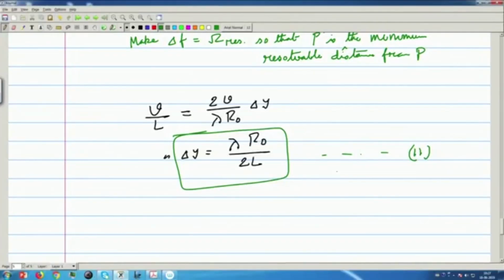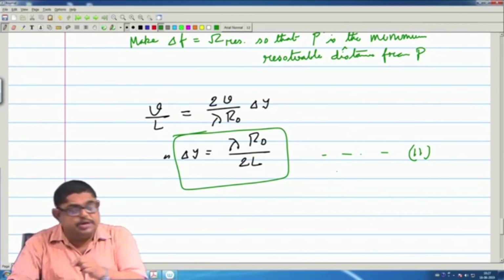We were discussing SAR systems, synthetic aperture. Now, we have found the cross range resolution, and we have seen the Doppler shift of the signal due to the SAR motion. Remember that Doppler frequency of each signal is almost linearly varying near t is equal to 0. Near t is equal to 0, that quadratic variation becomes almost linear.